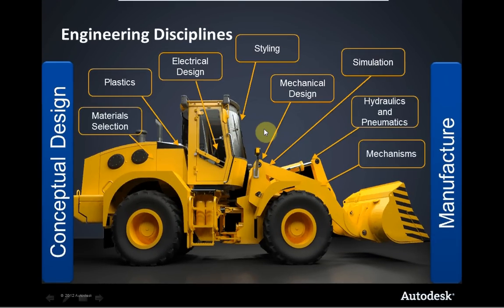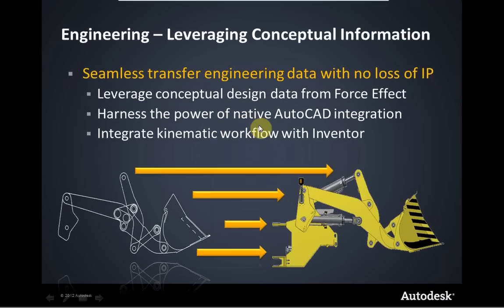Okay, let's have a step through on what's available in the Product Design Suite that a company would find of use. So first of all, we have the ability to work from 2D to 3D. The workflow is that you may want to try some designs out on perhaps AutoCAD or AutoCAD Mechanical in 2D with, say, blocks, for instance. And then once you've got these blocks created in the 2D environment, bring them across to Inventor to try a mechanism out and then convert to 3D later, so you don't have to model in 3D immediately.